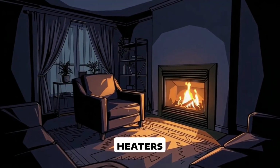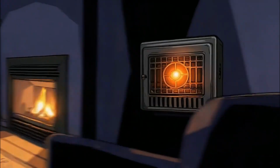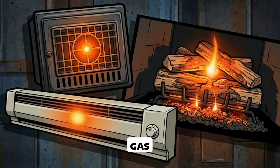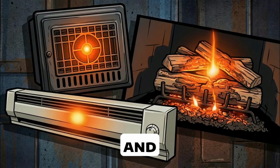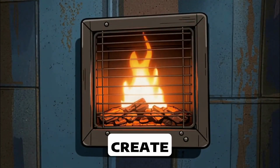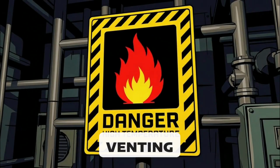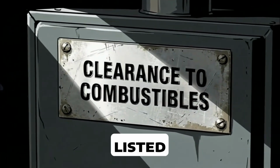Now, room heaters and decorative appliances. Examples include wall furnaces, baseboard heaters, gas fireplaces, gas logs, and room heaters. These create localized heat, but also create hazards such as burn risk, venting concerns, and clearance issues. Always follow listed clearances from combustibles.